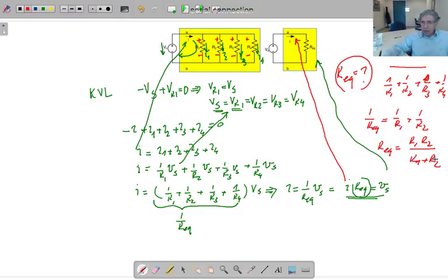You can say something about this result. How can you say it? I can say that if there are two resistors connected in parallel, then the equivalent resistance value is smaller than the smaller resistor's resistance value. A bit long, but if I give an example, you might understand it more clearly. Let's say this is 100 and this is 50 ohms. Then the equivalent resistor, which is the parallel connected resistors' resistance, is going to be less than 50 ohm, less than the smaller one.